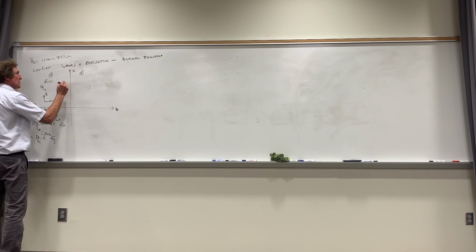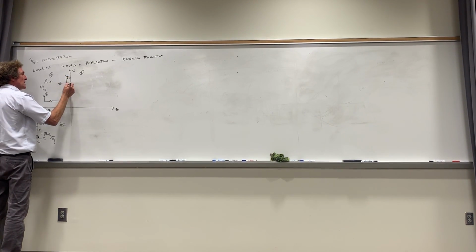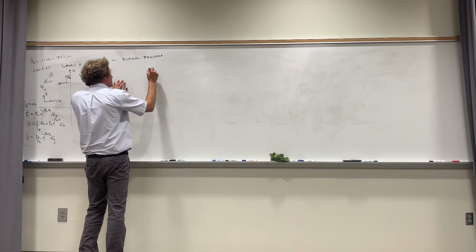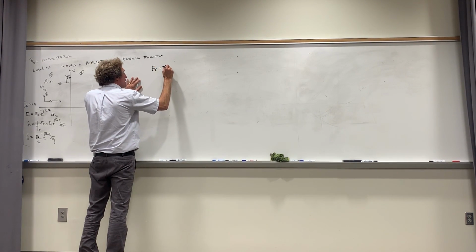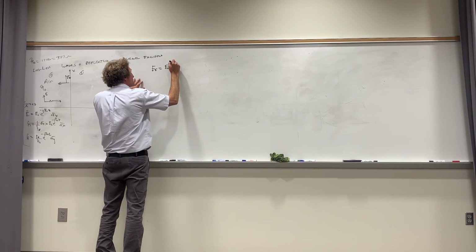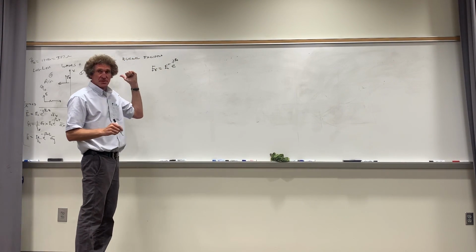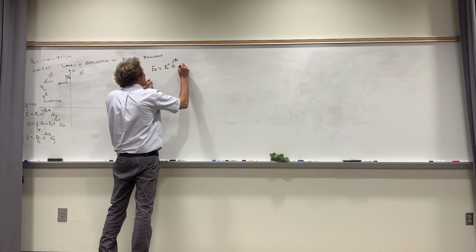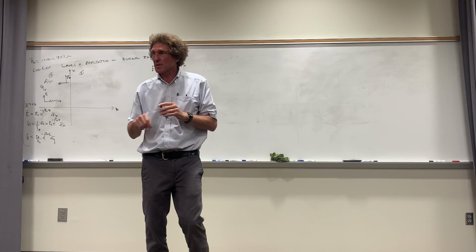So here we're going to get a reflected E field, and the reflected field will be equal to some E naught reflected times e to the plus j beta naught z. It's not going in the positive, but the negative z direction. Follow me? And the E field will still have the same a_x orientation, but now it's moving the opposite direction. Are you with me, class?